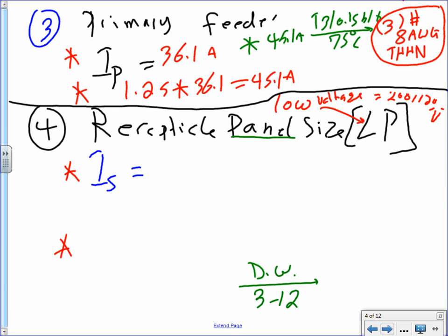The code references the motors directly. But for 3-phase equipment, you're defaulting to 75. Any questions about this? Why 3 conductors? Why 3, not 4? It's a delta, right? We're bringing in a delta. Delta-Y transformers.